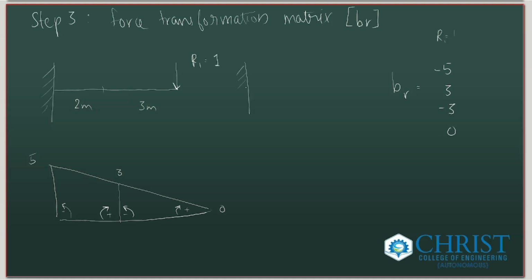Now we can do the same for the condition where R2 is equal to 1, and from our question, R2 is a unit moment that is being applied. The bending moment diagram for this condition would be this.